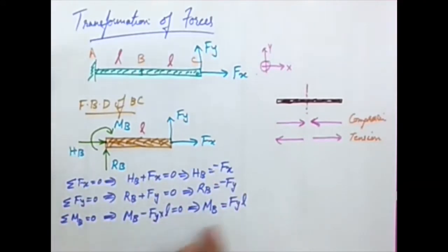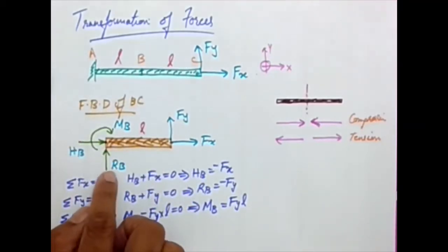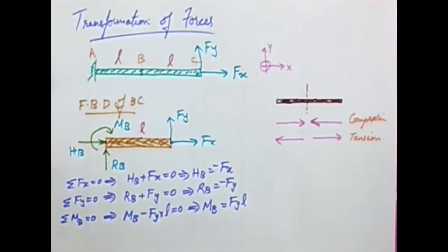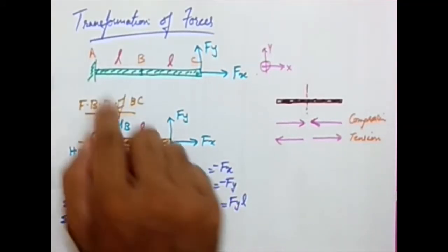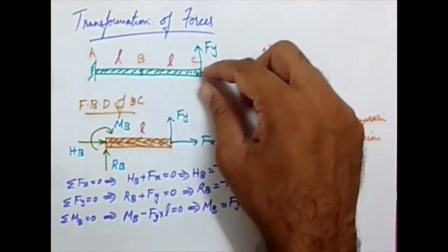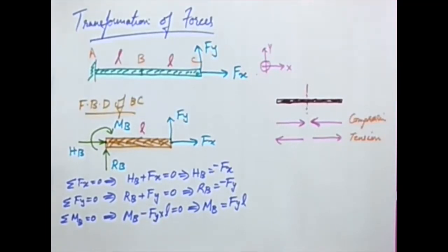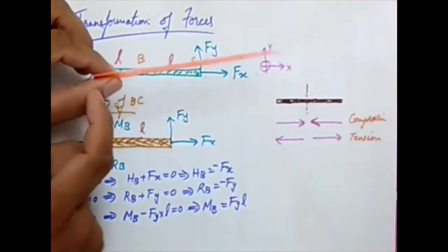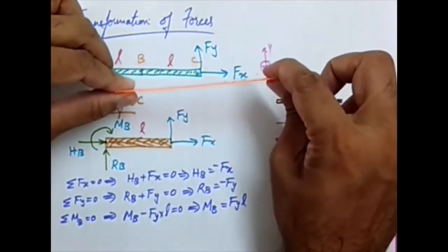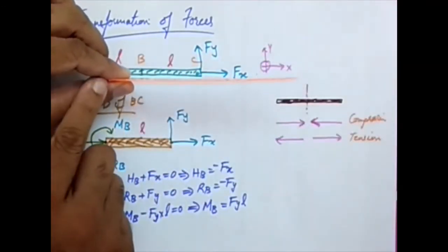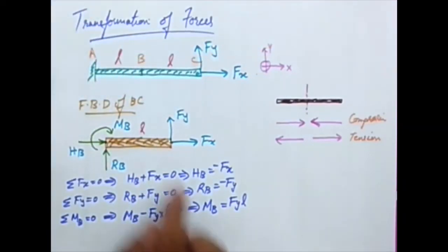Okay, so now we have all the forces or the reactions when I cut a section at point B. So I have the magnitudes and direction of all these reactions. So now this BC beam is in equilibrium. So what are basically these things? We know that these are RB, HB, MB, these are all reactions, right? What is causing this reaction in this beam? These are the reactions produced by the part AB, right? When I'm trying to pull this part BC, what happens? When I'm trying to pull this part, AB is going to resist. Okay, so whatever I got are the reactions exerted by AB.